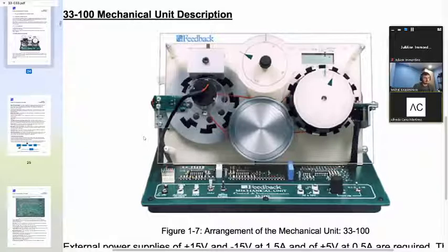So you can think of this feedback system that we've been using as trying to match voltages. In the case of our system, the voltages have a physical explanation because we have mapped them to position, or angular positions, right? So the whole idea behind this system is that we're basically just comparing voltages. Now you ask yourself, how do you get voltages? Well, you set up a transducer that transforms a physical unit into a voltage. This is what all feedback systems rely on.